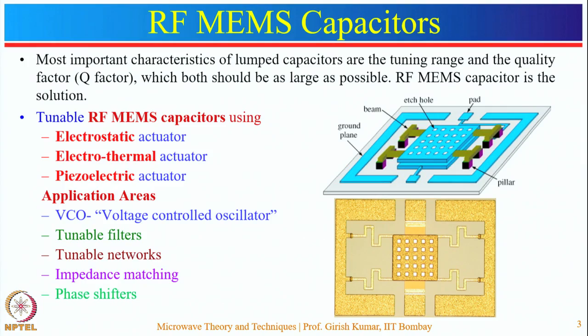For most wideband applications, performance is given by the electrical parameters of capacitors, which are wide tuning range, low phase noise and wide bandwidth. In case of capacitors of semiconductor type, they do not provide a wide tuning range at higher frequencies.